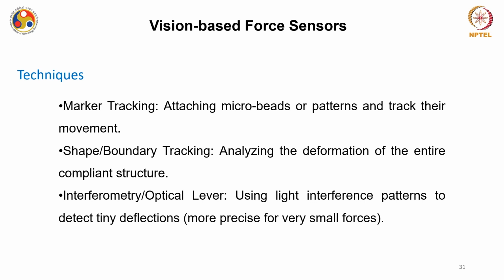Then interferometry or optical lever based analysis also exists, using light interference patterns to detect tiny deflection, particularly when the microstructures are in the range where these interference patterns can be generated.